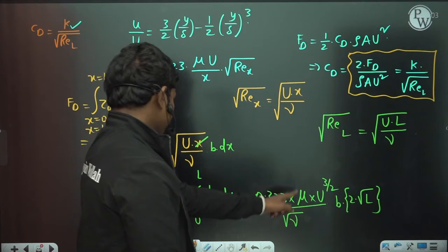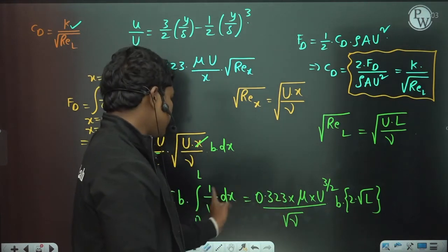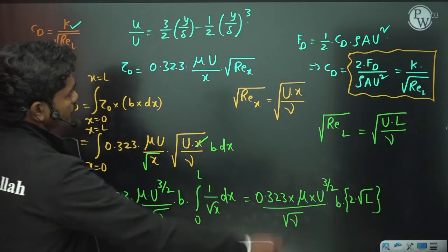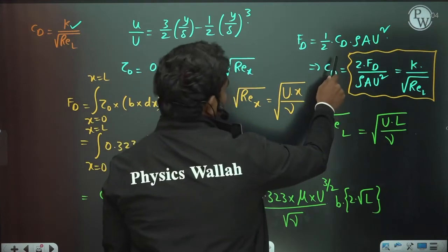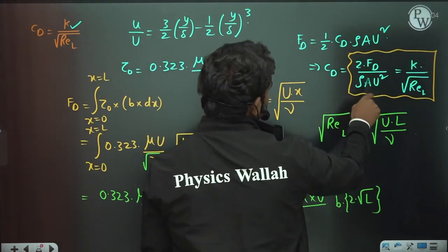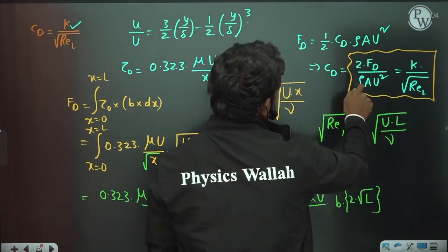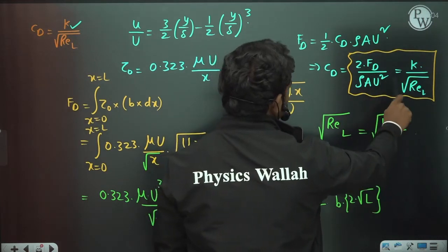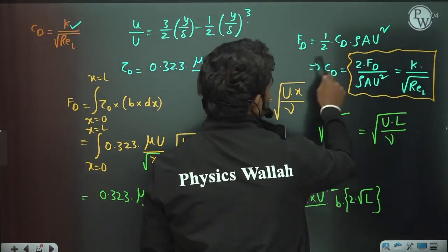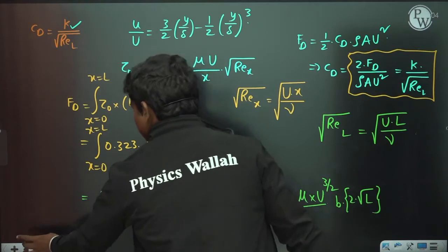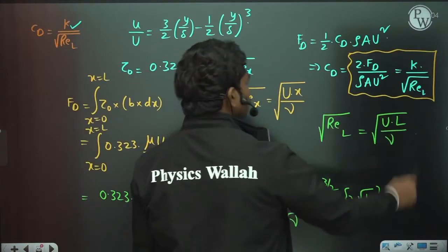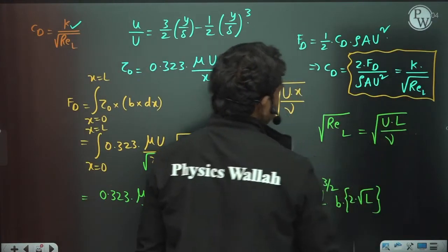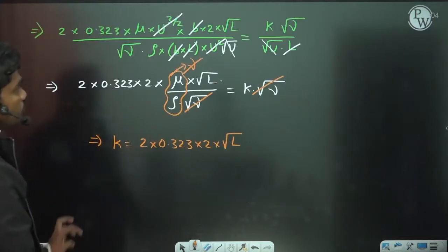So this combination is as it is, integration of this is 2 times root L, and here half C_D times rho A u squared, so C_D is equal to 2 times F_D by rho A u squared. This is equal to coefficient of drag, which is also given by k by root Re_L. So this is k by root Re_L. These two expressions are the same, so if you equate them, we'll get...